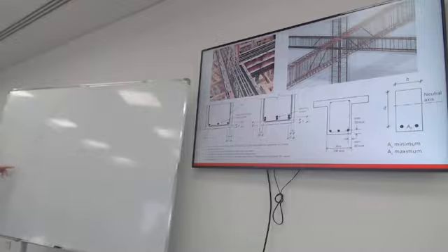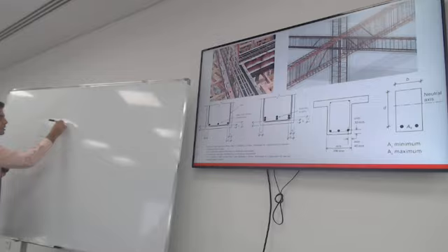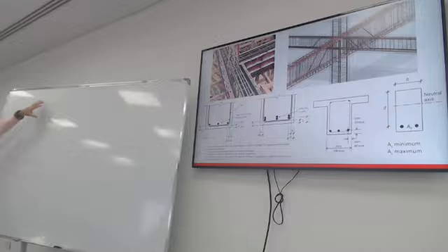The crack will extend up to the point where there is no more tension. This line is called the neutral axis. So what is the neutral axis? It's the line above which you'll have compression and below it there is tension.